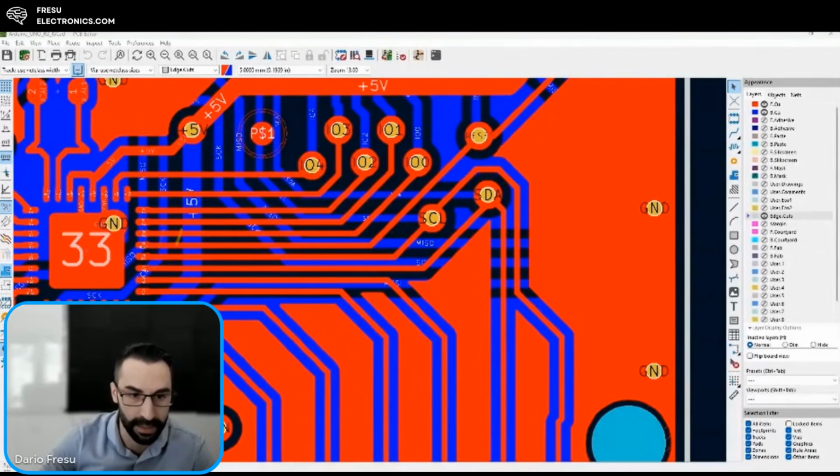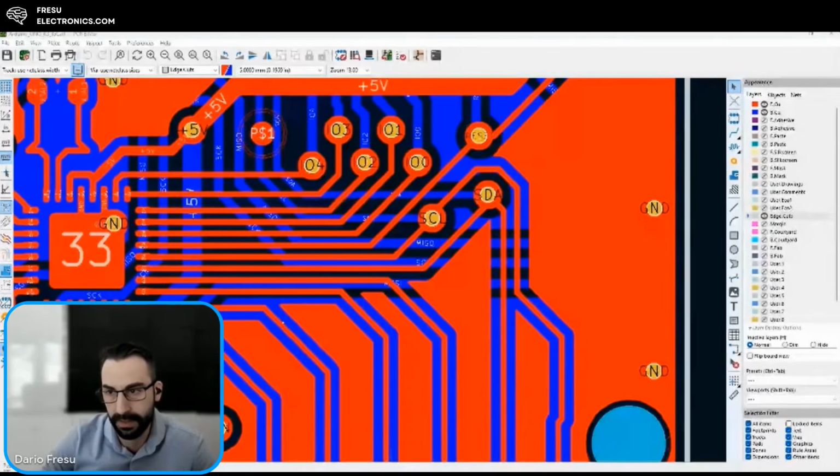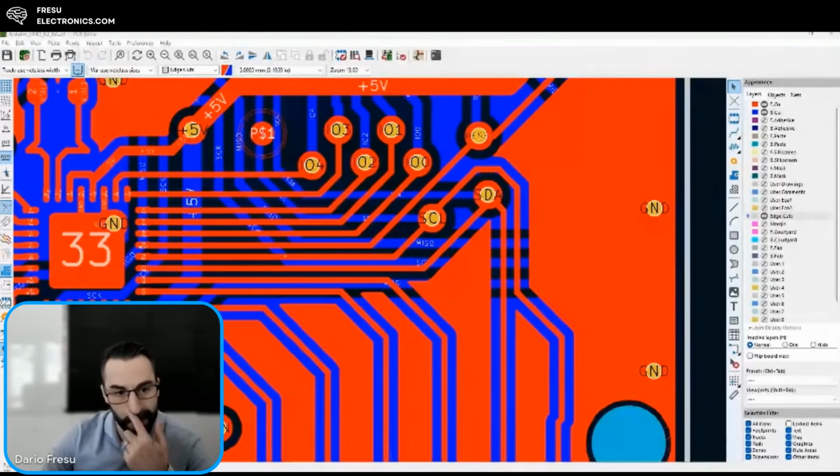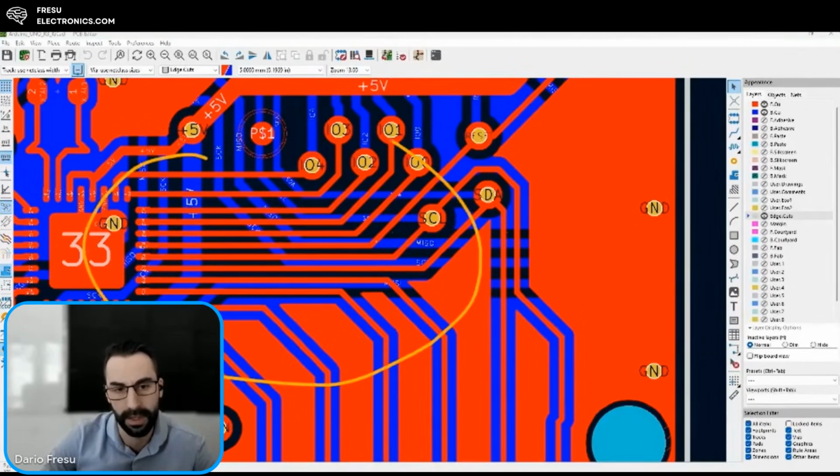So it's essentially going to establish a field which goes like this, and then it spreads along the lowest impedance path. Where there is the lowest impedance path, in order to conserve energy and not spend too much energy on the propagation, it is going to be established between all these copper structures, but also between the top layer and the bottom layer. So whatever field I try to establish in here, at this point, is going to couple with all the structures that I have in between.